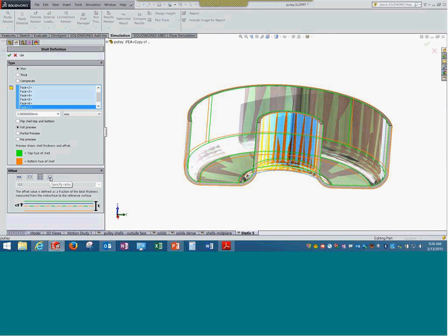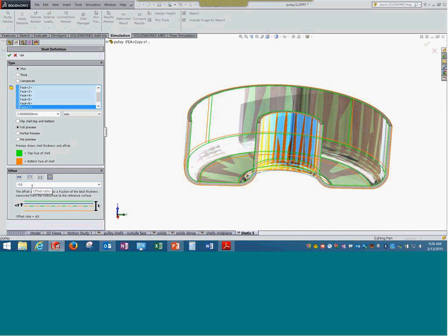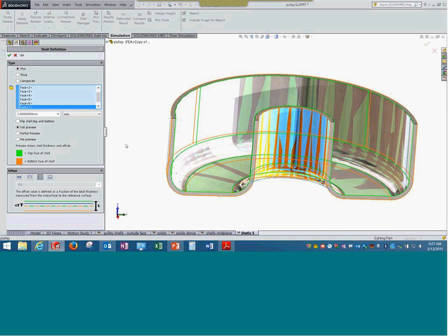And just to show you, there is one more option called specification. It may be rarely used, but there could be a case wherein the selected surface is actually offset or away from the actual geometry. These are relevant especially in those cases wherein there are gaps created intentionally or because of the modeling conditions, probably creating an edge or certain surfaces there, whereas the other part is a solid. When you come across those geometries, you'll automatically understand that this is the more relevant option. In this case, it is obvious we are selecting the bottom surface that represents the geometry appropriately.